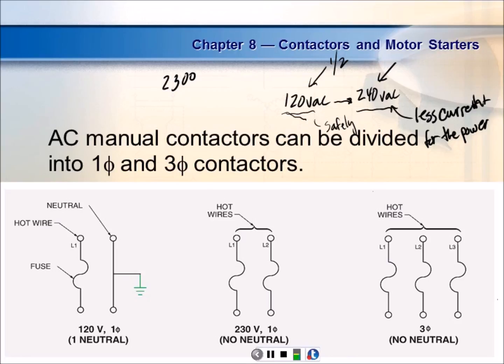And of course, if you have a device designed to run on 240, and all you got is 120, and you decide you're going to rewire it, right? I mean, you got 2 wires coming out of there and a ground, but in 240, the 2 wires are hot. In 120, one is hot and one's what we call neutral. So what would happen? Well, it's going to try to produce a quarter of the power, and it's not going to do any work for you, right?